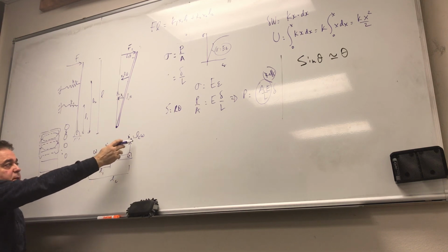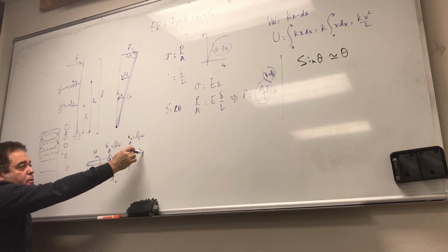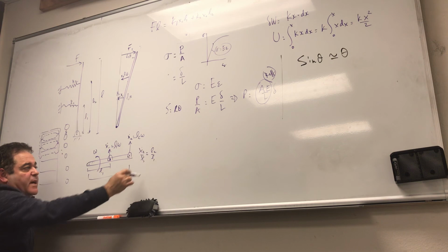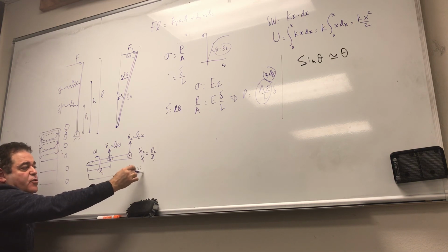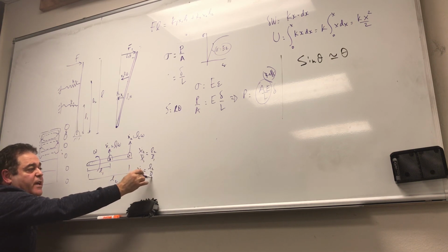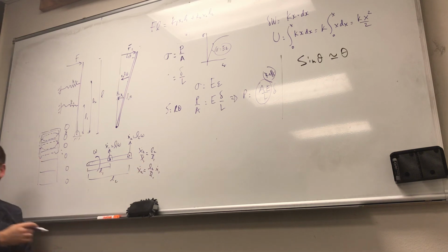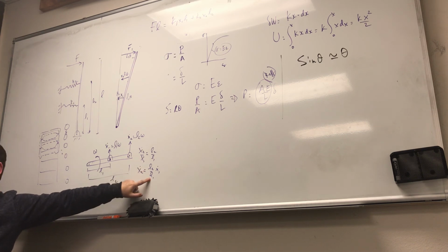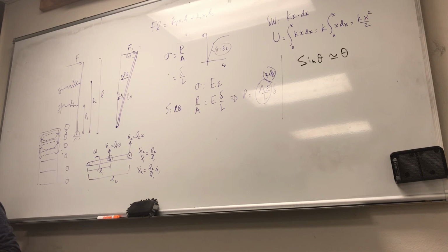So really, if I take x dot 2 divided by x dot 1, what do I get? The omegas cancel out, so it's going to be L2 divided by L1. So x dot 2 will be essentially L2 over L1 times x dot 1. By the same token, x dot 3 will be L3 divided by L1 times x dot 1. That's why you see that equation right there.